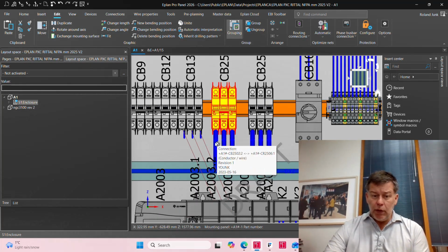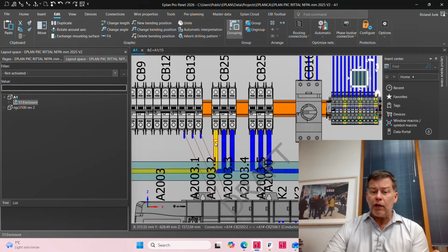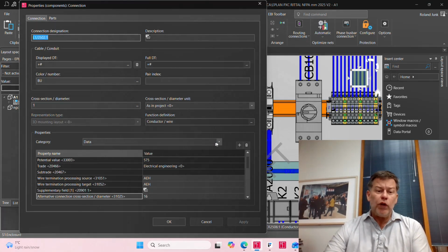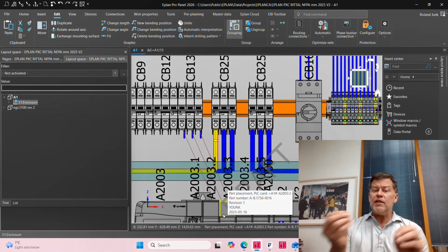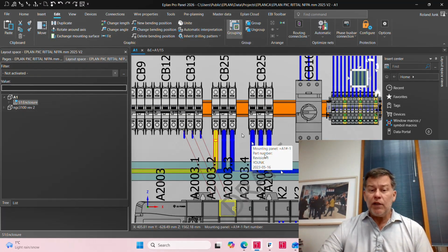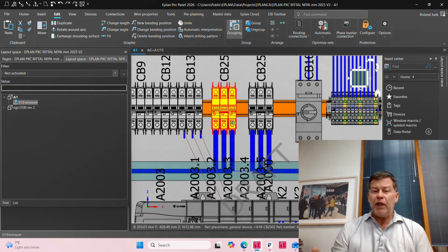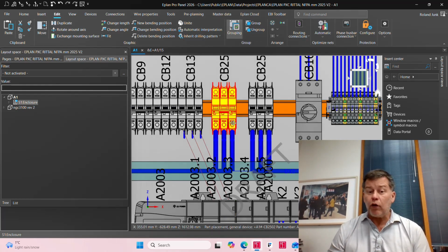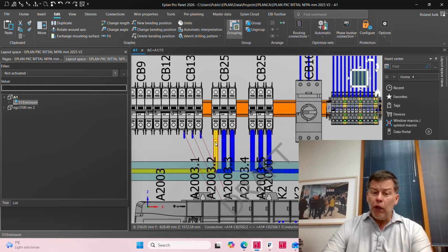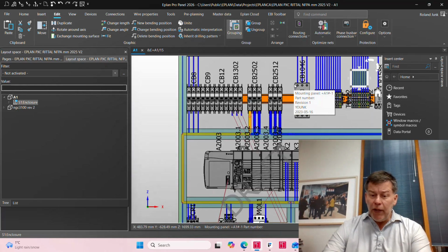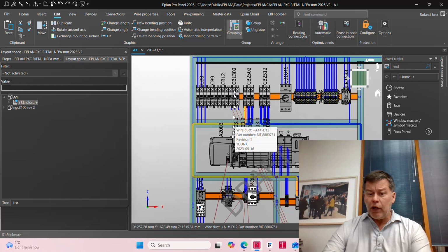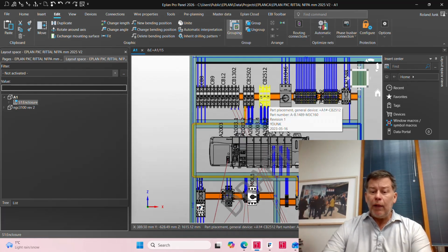Now, this enables us to calculate the wire length. So every one of these wires now has a specific length, and this length can now be pre-cut. We also know what is at both ends, because we know it's a screw connection, so based on what we typically use, like a ferrule, we will know what it is. And how does it know where to go? Well, the source and target of the routing is provided by the schematics.